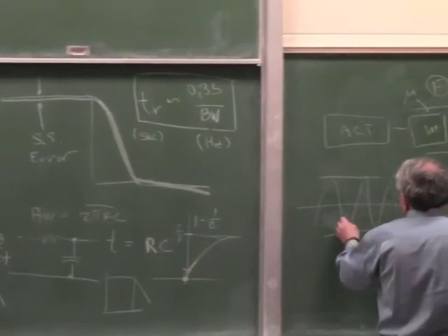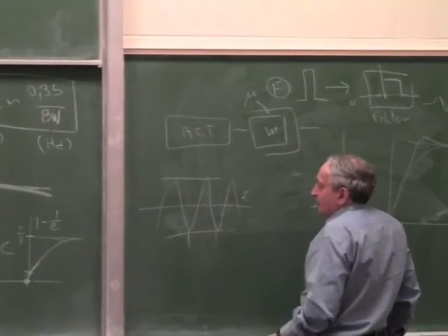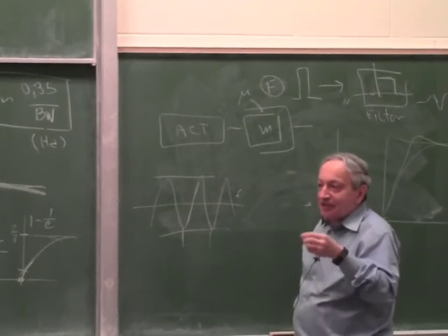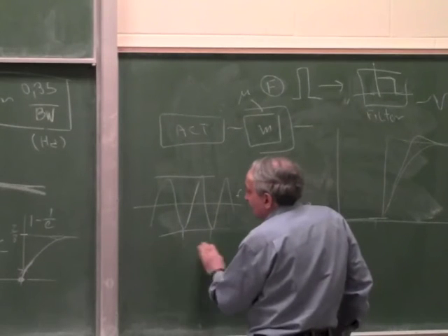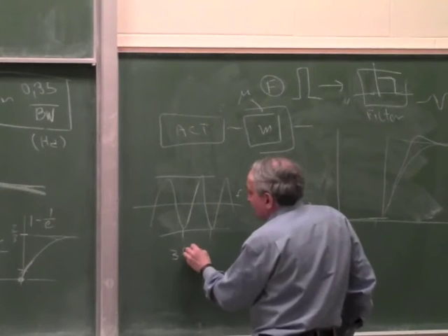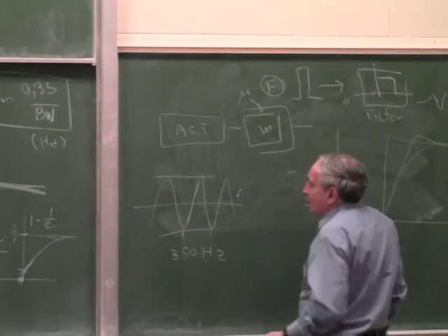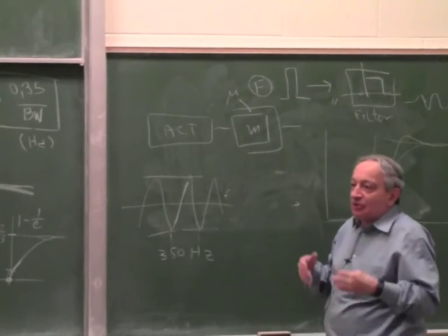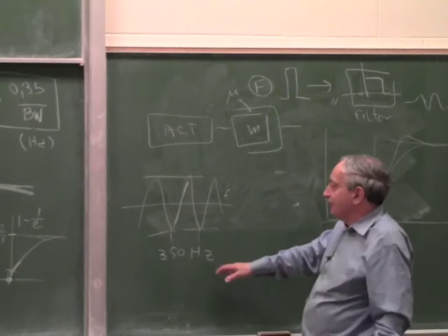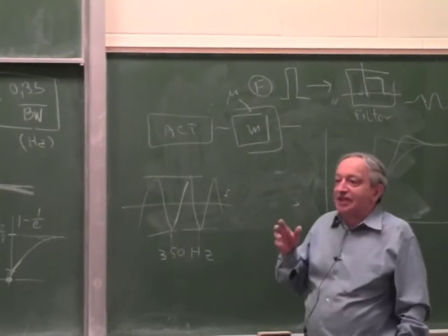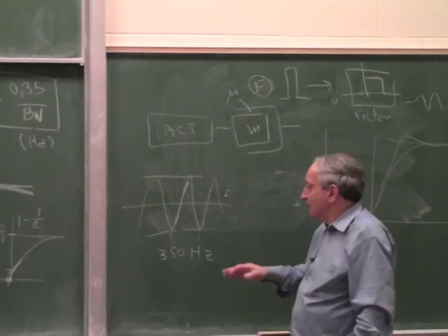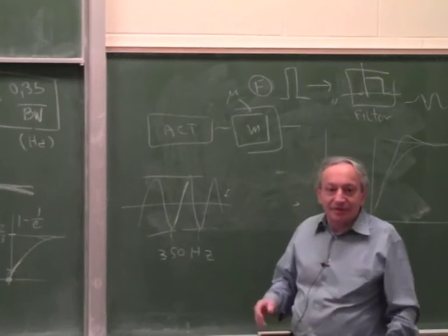The rise time was a millisecond, but the total number of cycles per second was not 1,000, but only 350. So if you can calculate the energy needed to do one cycle, we can multiply with 350, we get the power.